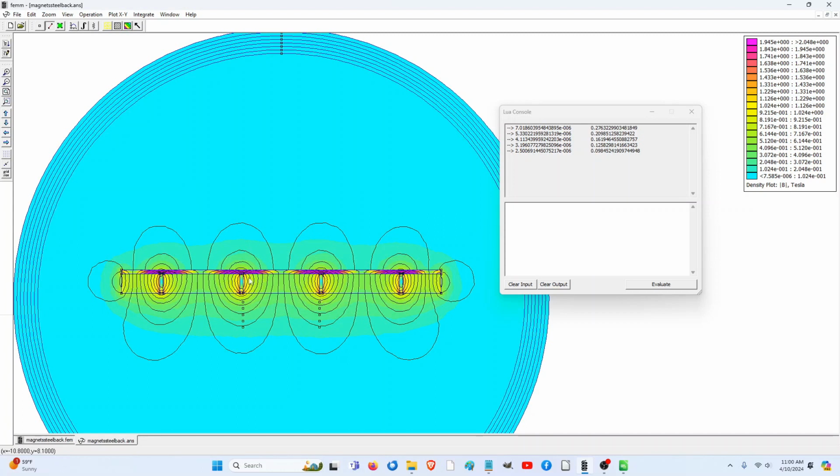So I could specify the thickness of the steel, and in this case I wanted to use a circular saw, and that was 0.12, or 1.2 millimeters in thickness. So I got steel there, and this magnet here is showing an N52 magnet. We can specify that, and then there would be a gap. This is the magnet here. There'd be a gap, and then the coil would start here.